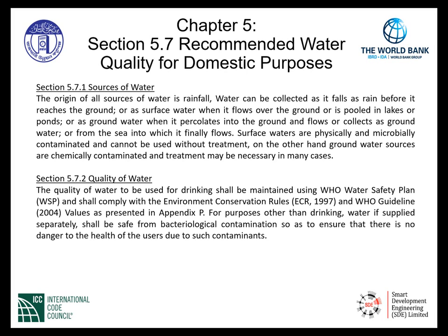The quality of water to be used for drinking shall be maintained using WHO Water Safety Plan and shall comply with the Environment Conservation Rules, ECR 1997, and WHO Guideline 2004 values as presented in Appendix P. For purposes other than drinking, water, if supplied separately, shall be safe from bacteriological contamination so as to ensure that there is no danger to the health of the users due to such contaminations.